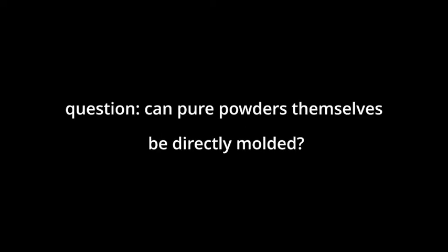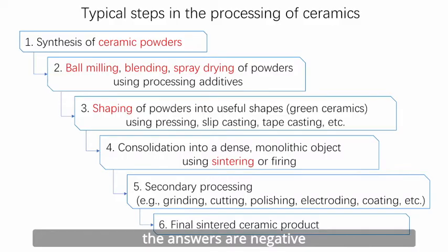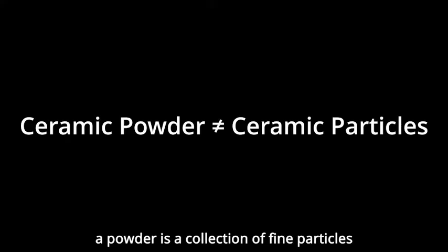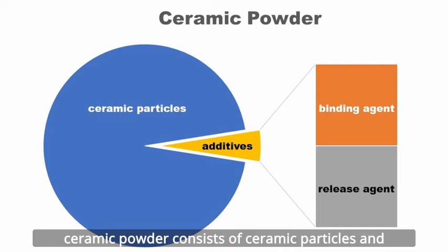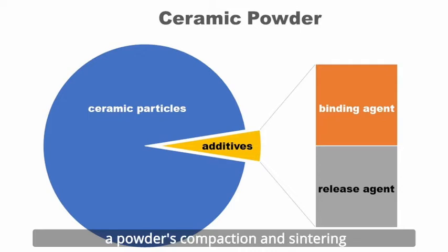Question: can pure powders themselves be directly molded? The answer is negative. This is where the second step is necessary. A powder is a collection of fine particles. Ceramic powder consists of ceramic particles and additives that improve the powder's compaction and sintering.